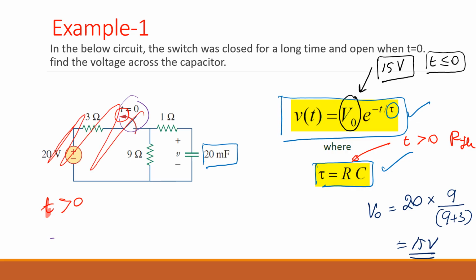Agree? And what is happening here? You have a circuit like this. Am I right? Agree? And we need to find the resistance, open circuit resistance across these 2 points. That will be your RTH. That's how we find the RTH.